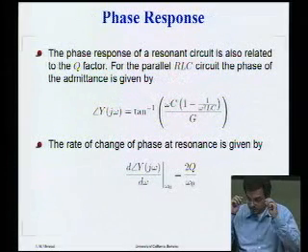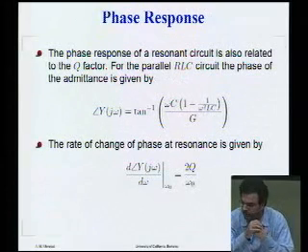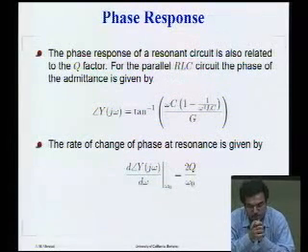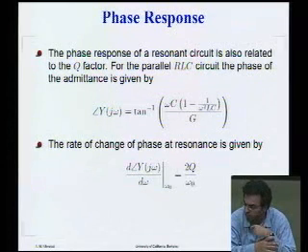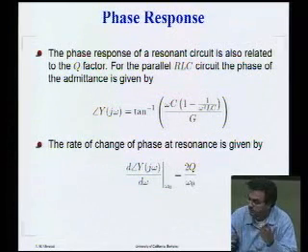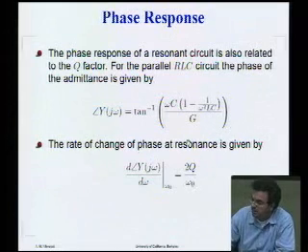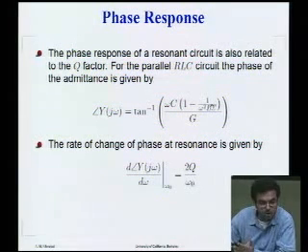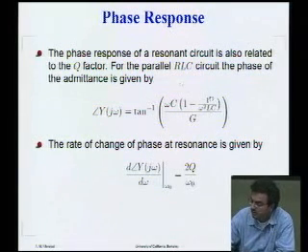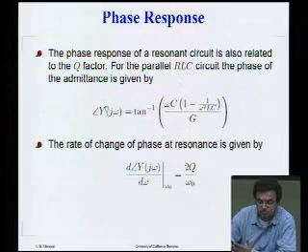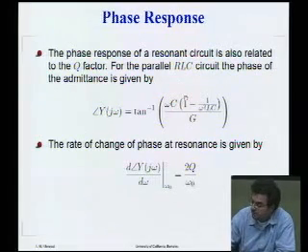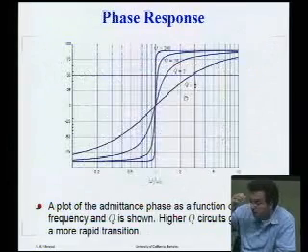Okay, so we spent a lot of time talking about the magnitude response. It turns out that in many applications the phase response is also equally important. And it's very simple to find the phase response. It's just the arctangent of the imaginary part divided by the real part. This is the imaginary part in the circuit. This is the real part. And basically I can now plot this. So I'll come here and do several plots.